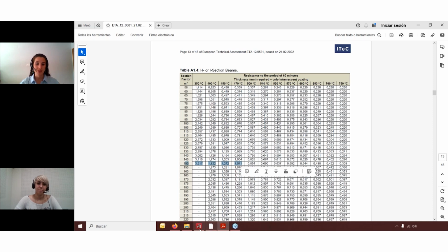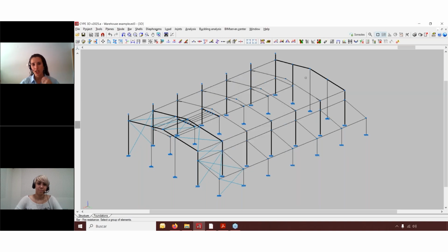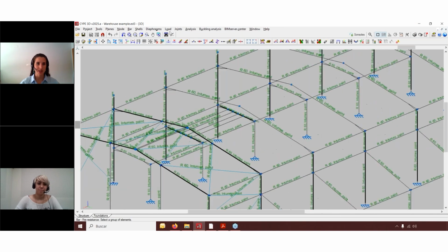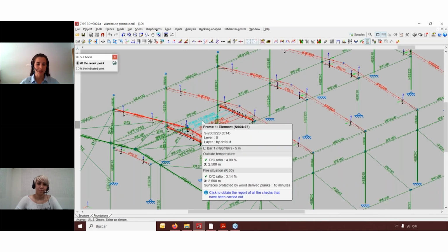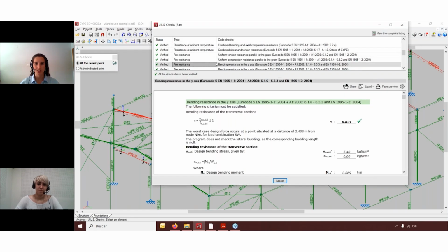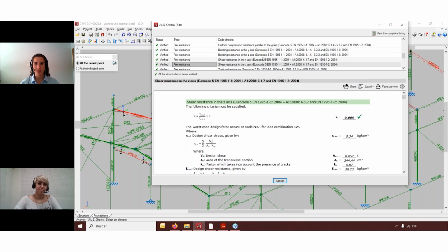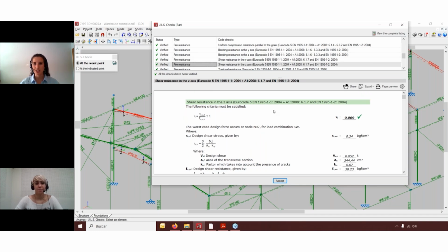So it's very useful that you can now select which exposed surfaces you have for bars. So yes, you have the example here that the analysis ULS checks that for timber sections we also do fire resistance. According to the code selected, we check both steel bars and timber bars.